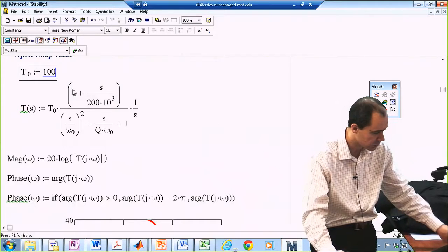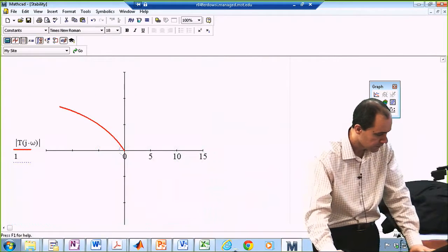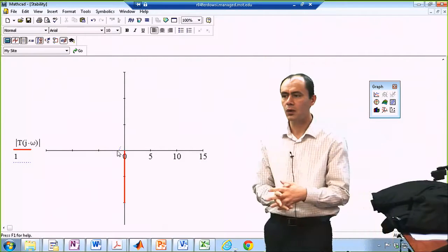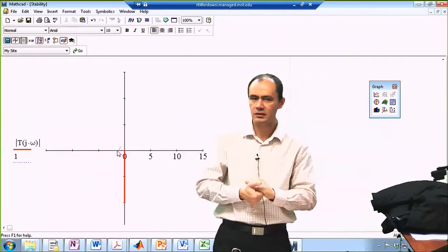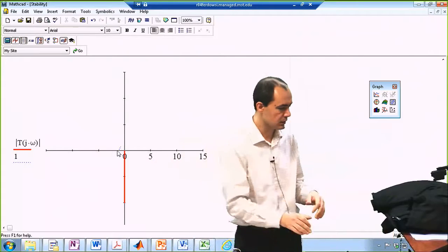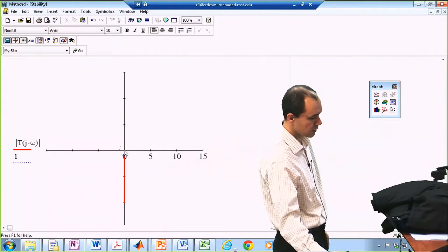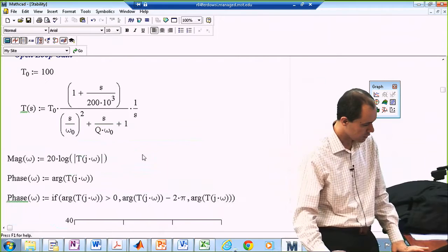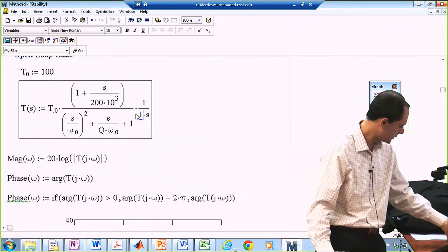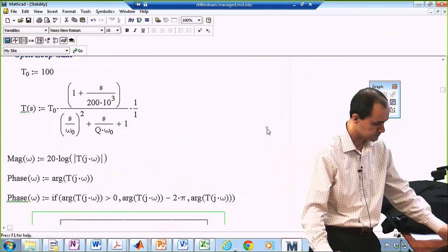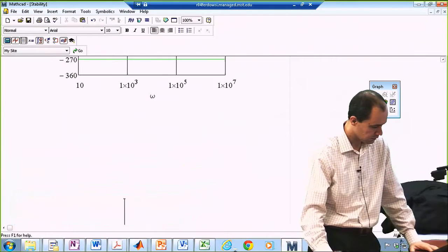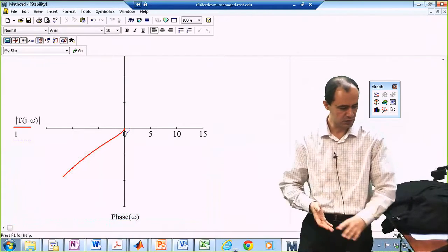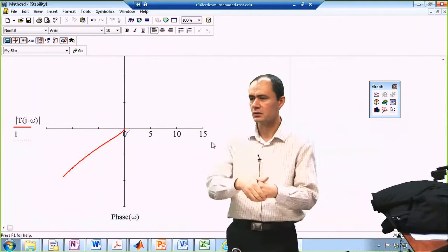Let me just go back to the normal gain of, for instance, 100. It is all about how many times you're circling around the point -1 in the complex domain. If you're not circling around -1, your system is stable. Like over here, -1 is here and my graph is all over here, so no problem. Let me show you a normal Nyquist. Let me just eliminate this to 1. Usually it looks like a half circle, or something like that.